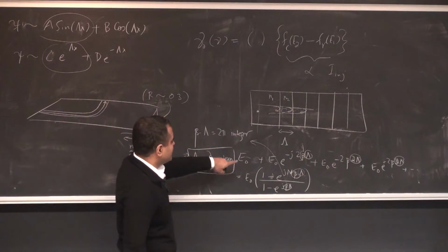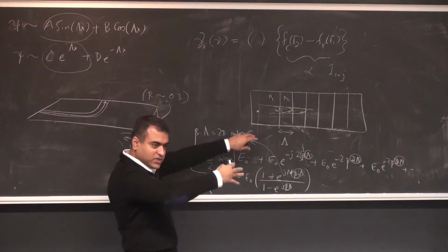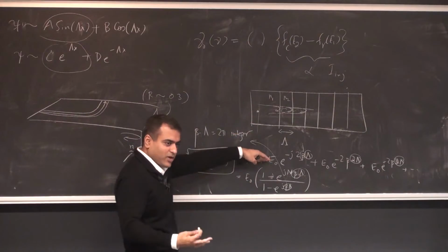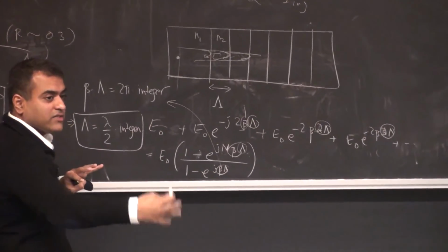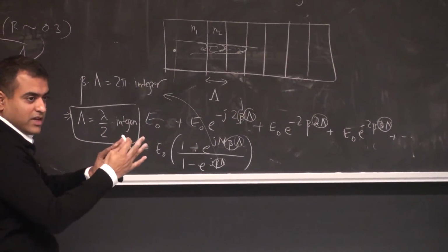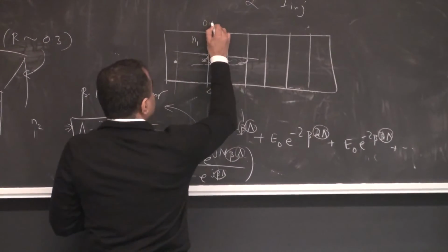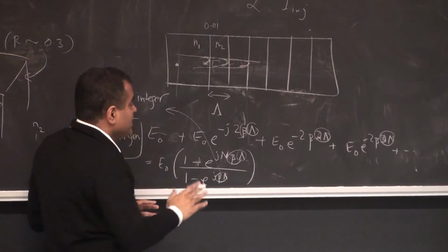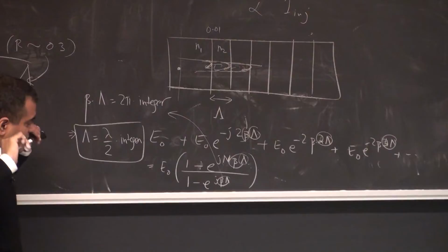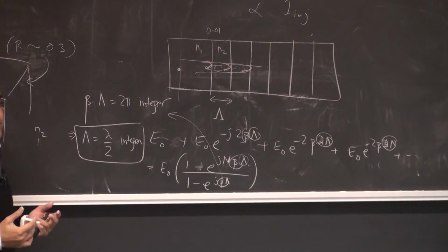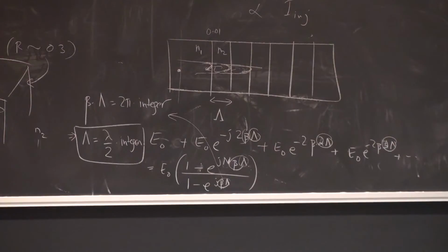In fact, if you go back and look at our cavity problem, when we studied the cavity, we took that into account. So it's the same problem, really, except now you have a periodic cavity where you have a periodic array of mirrors rather than just one. The difference is each mirror has a very small reflectivity, maybe 0.01. By putting enough of them in a periodic array, you can get back 100% reflectivity over a small window. That's the message here, and that's the distributed Bragg reflector.